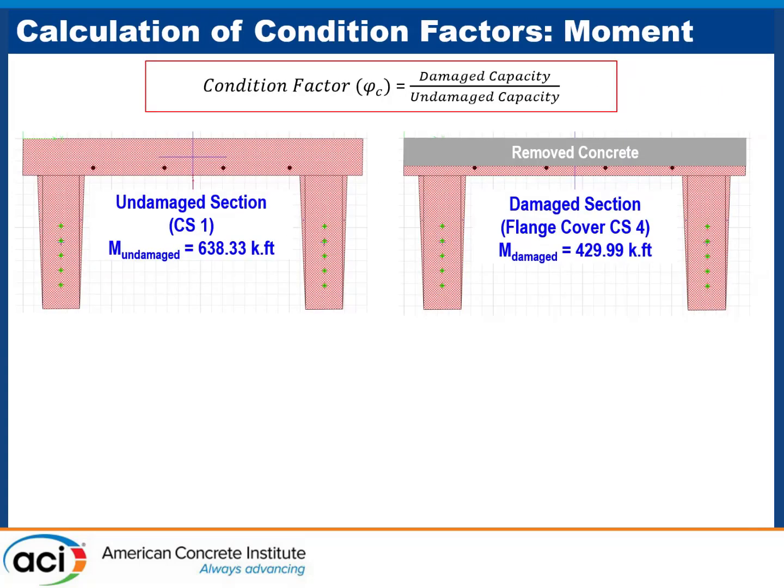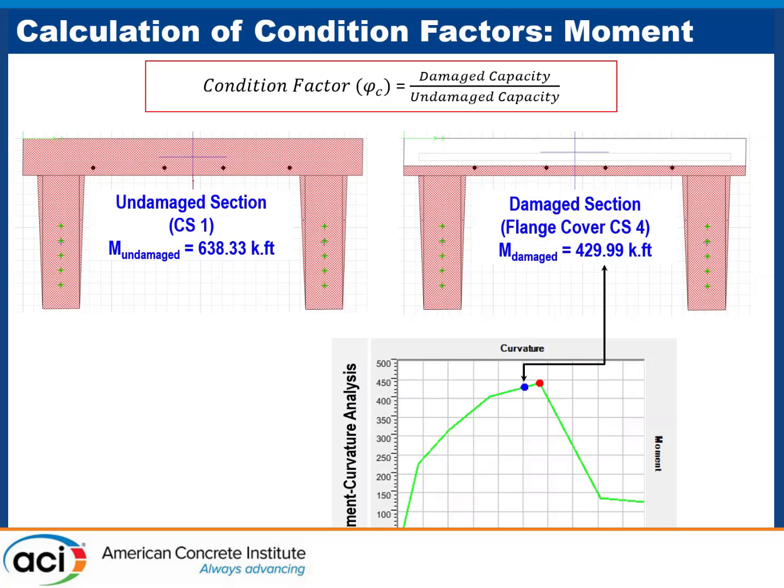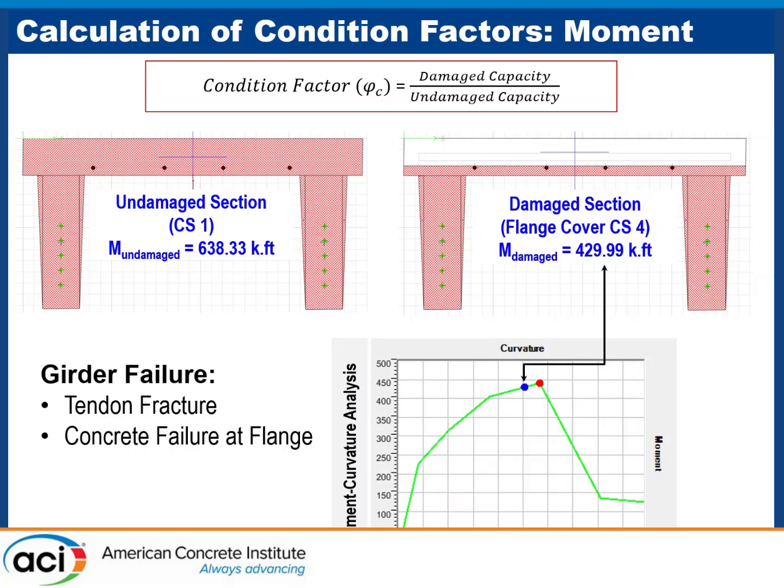If this girder is the double T that you have, and you are playing around cover deterioration, take out 25% of the entire cover, 30%, 40%, whatever your damage state will call for, remove concrete, do a moment curvature with and without those damages. The ratio of the peak moments are your capacity reduction factor. We did that not only for one girder, for 25 girders, not only one damage, all of those that you saw in that color table.